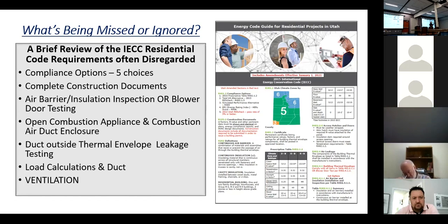So we have literally 1/5 of the amount of insulation. But what's our delta T? It's 85 instead of 65, because the air for the air conditioning system is 55 degrees. So 55-degree air in the duct, R8 insulation, and that heat outside. I've taught, I don't know how many Manual J, Manual D classes in St. George. Between 25 and 50% of their cooling load is to overcome heat gain from putting that crap in the attic.